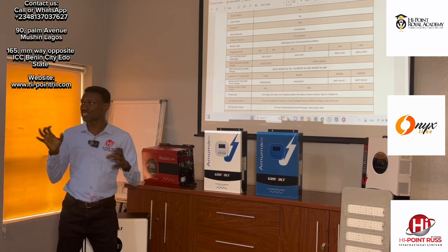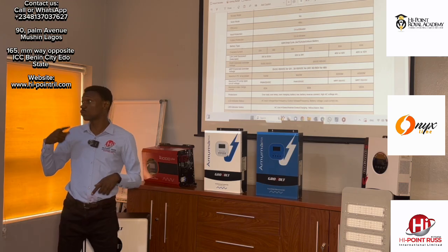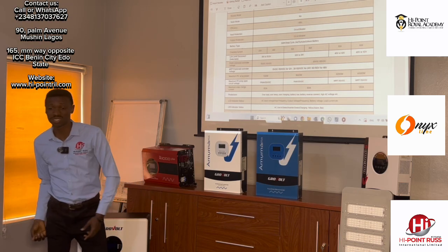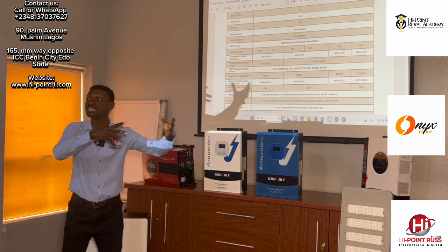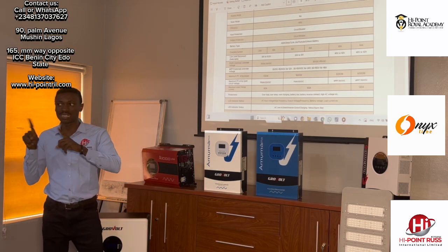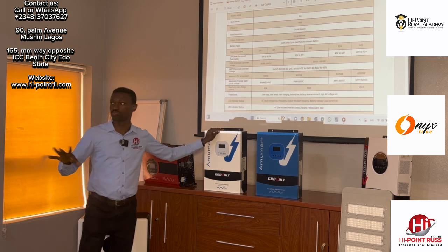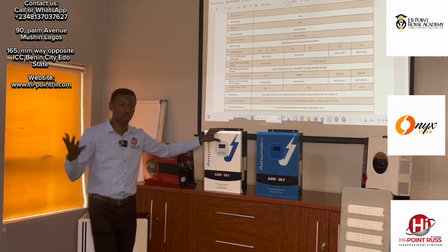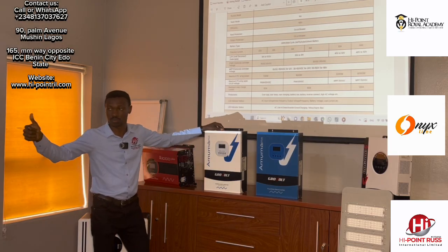I don't know if you've ever suffered something like that. When you're stranded, there's nothing more, and it can be particular with some brands too. Once you're stranded, there's nothing more you can do. You have to take down that battery and send it to that company's service center. Maybe that's how they will boost it or wake up the cells and then give it back to you. We've suffered that kind of problem once or twice in the past. But with a good lithium wake up function, even if that battery has drained to the end, it will take its time to boost charge it. It will come up. So to some extent, lithium function is very supported.